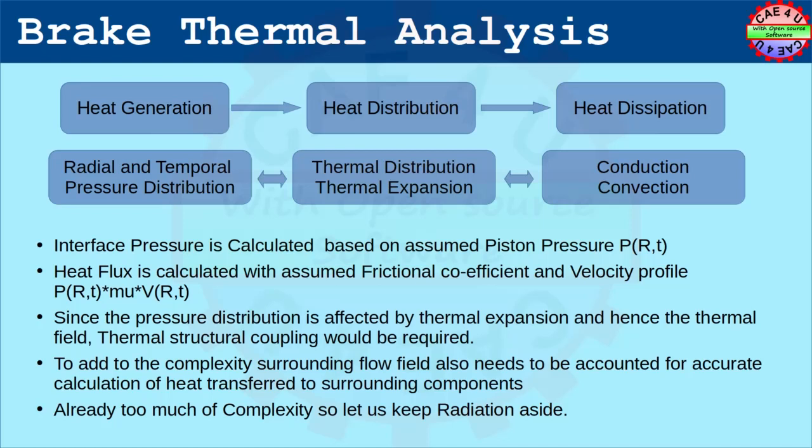The axial force creates a radial and temporal pressure distribution across the interface, which creates the heat. It can be numerically calculated as the pressure distribution multiplied by the frictional coefficient between the surfaces multiplied by the relative velocity of the disc.